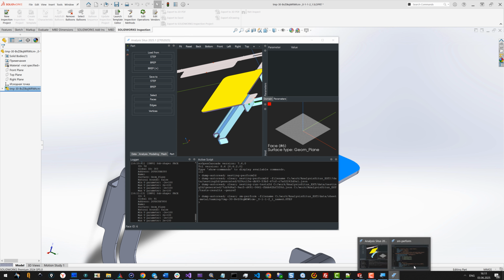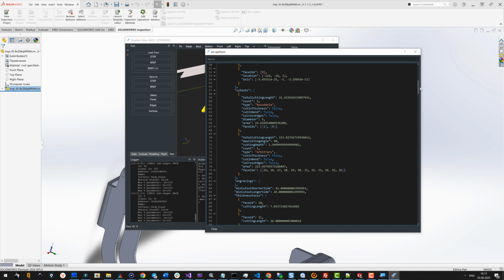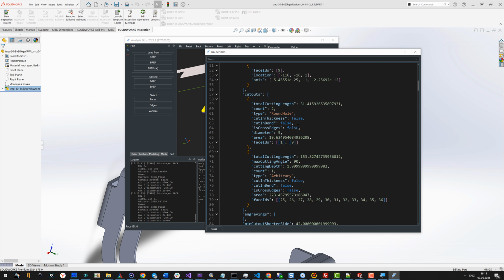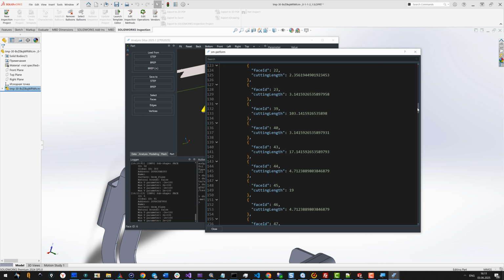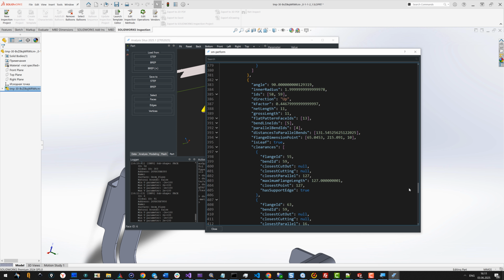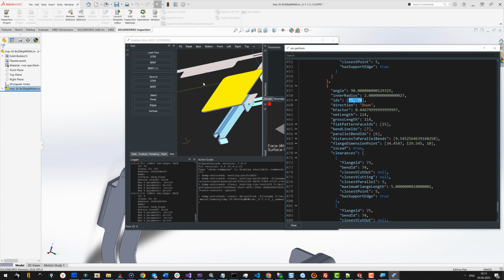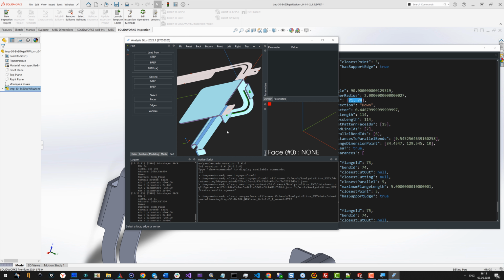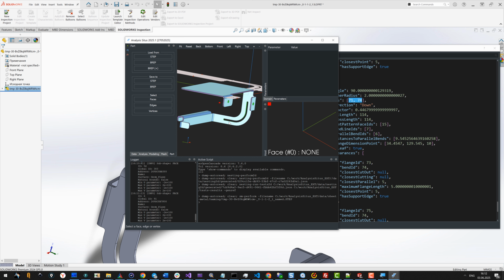So what it means is that if I take the recognition results from Analysis Situs, of course there are many properties reported and features like holes, bands, engravings, whatnot. The problem is that I would not be able to use those properties because I do not really have the same IDs in SolidWorks. So if I want to interpret those properties on my part, then I have to stay in the perimeter of Analysis Situs, or more generally in the perimeter of the Open Cascade kernel.